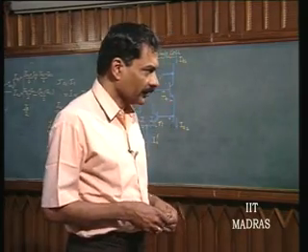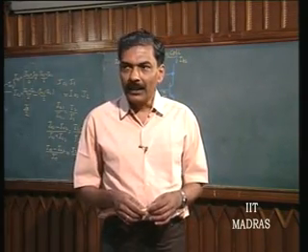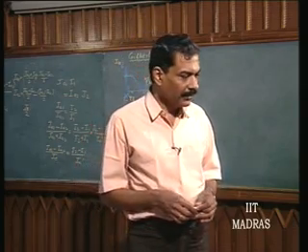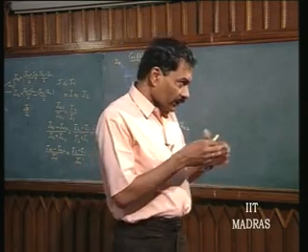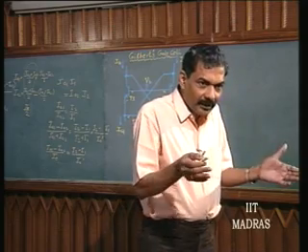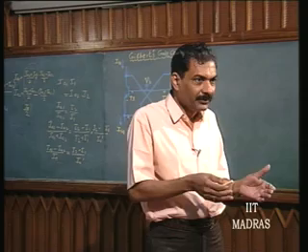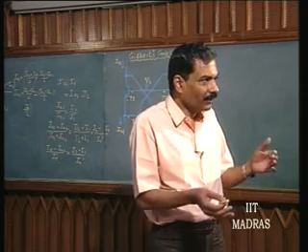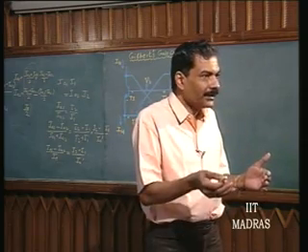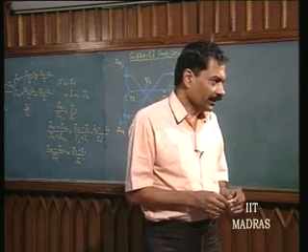This basic concept can be straight away adopted for video amplifiers or wideband amplifiers, because there is no need for negative feedback, because of the fact that amplifier gain is independent of device parameters. And if you do not have negative feedback, then the consequent problem of frequency compensation being needed and oscillation to be prevented, all these things are avoided.